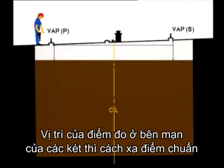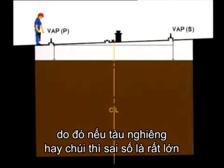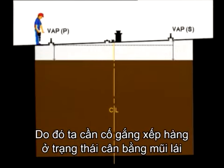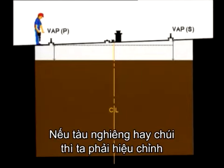The position of the measuring points in the sides of the tanks is far from ideal. The tanks are wide and the measuring points are away from the tank centre, so there will be a big difference if the vessel has a trim or a list. That is why you should try to load the vessel on an even keel and with no list. If there is a trim or a list, you must use the corrections.